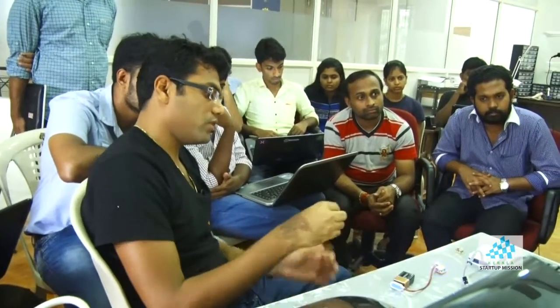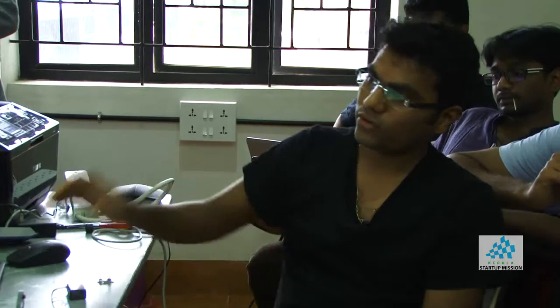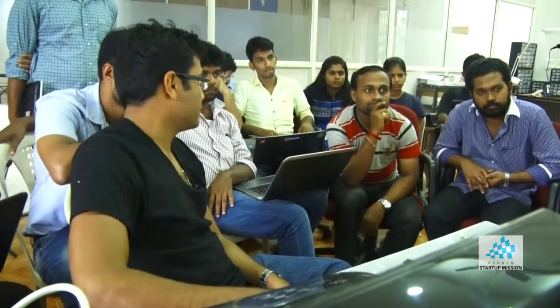Let's try to make a similar board. Here we are using the ATtiny45. I'm going to use the add command, hit enter. That will open up a window with all the libraries. Now I'm going to scroll to the Fab Lab library. One of them is Fab, and I can see there's ATtiny44. I'll see if there's a better version of that, ATtiny with ISP. Okay, let's just select ATtiny44, which is this one.